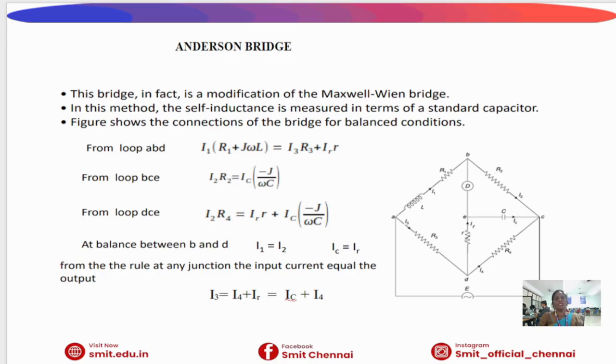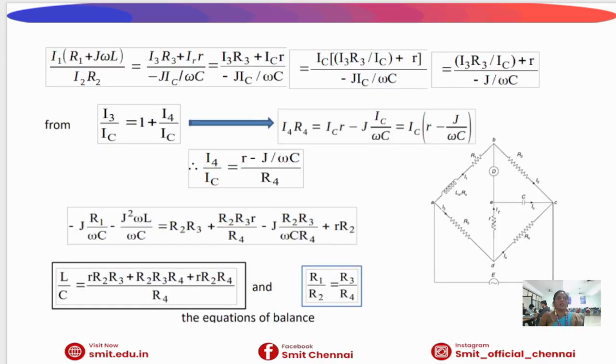The Anderson bridge provides high accuracy, precise inductance measurement, and use of a fixed standard capacitor instead of variable components. However, the circuit analysis is slightly more complex compared to the Maxwell bridge. Hence, the Anderson bridge is widely used for accurate measurement of inductance, especially in laboratory applications.